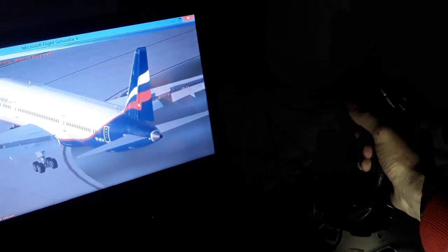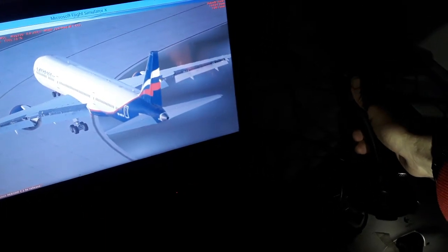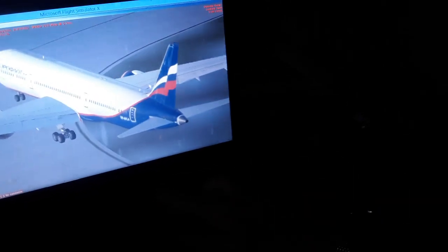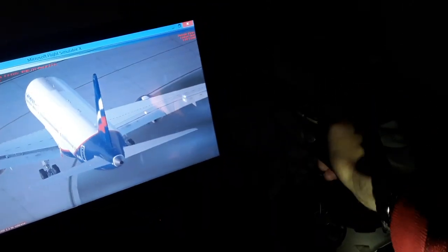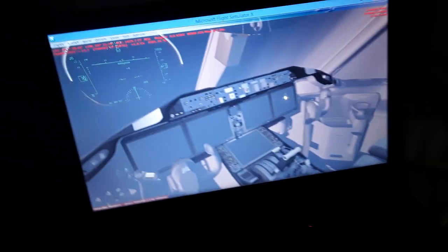Horizontal trim stabilizer also, we can trim the aircraft in flight. We can make bank rolls right and left and right. So we have full flight control system functional. The side stick deflection is proportional to the yoke and flight controls deflection, but it is a fly-by-wire aircraft. It has fly-by-wire computers, flight control computers, so it will deflect the way it should be for making Z turns, Z acceleration turns like the Airbus. So it has the flight control computers in flight.